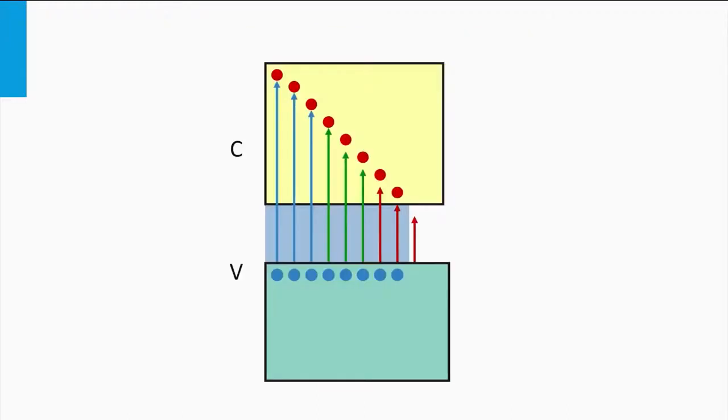If we now consider an absorber material with a lower bandgap, we see that more photons in the spectrum can excite charge carriers. This material will result in large short circuit current densities. However, due to the smaller bandgap, the splitting of the quasi-Fermi levels and the resulting open circuit voltage will become smaller.